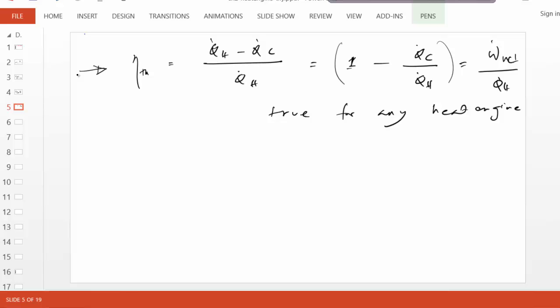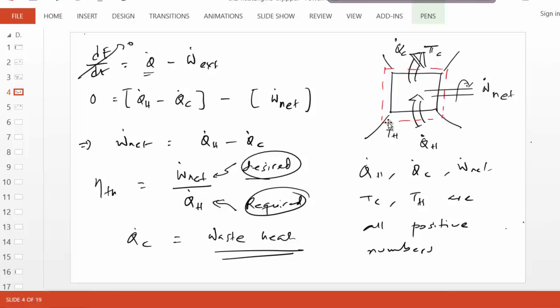All right, let's do a second law analysis, just to make sure the second law is not violated. So we start with the entropy equation, Q dot over T boundary, recall. And now I want you to follow the next step carefully. What should be substituted for Q dot over TB? Let's look at the boundaries. Well, there is a Q dot going on here. Q dot over TB means how much entropy is carried by heat. Would you agree that the heat going in is carrying entropy and heat coming out is carrying entropy out?